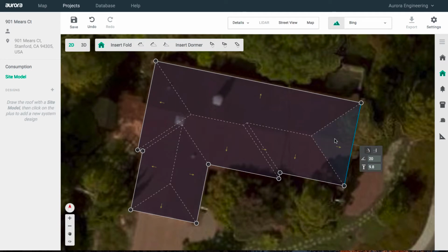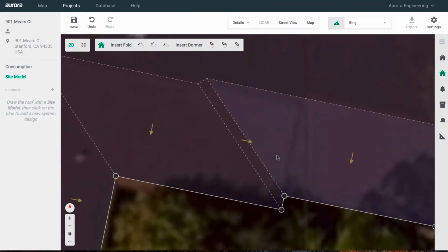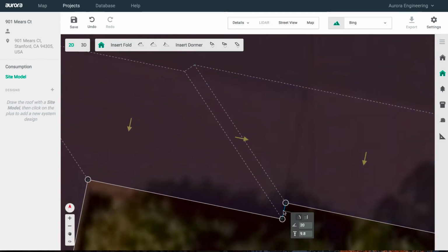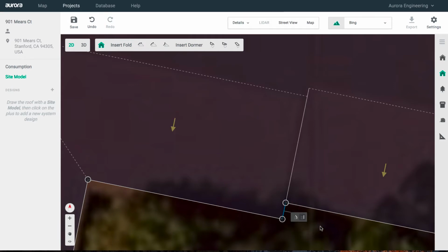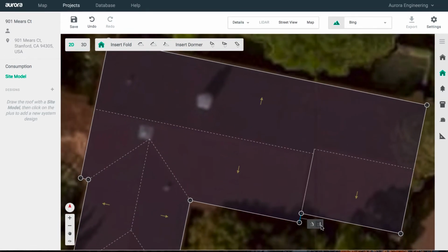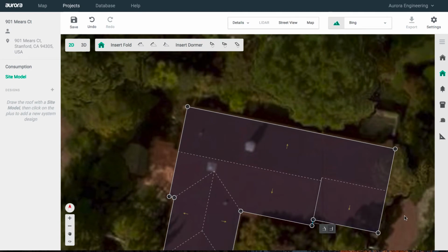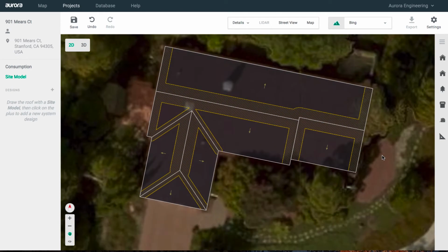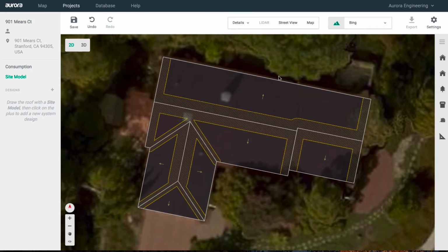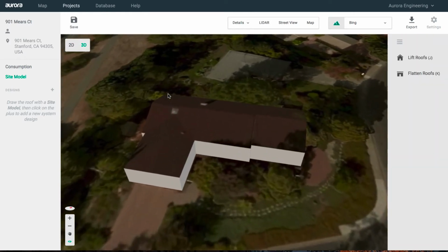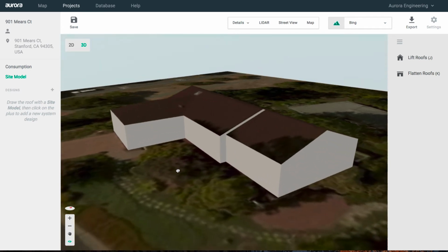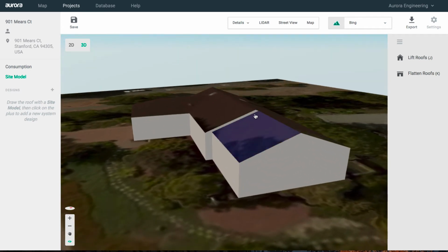Alright, next we're going to open up those edges because this is a central ridge line that runs across. And I'm going to do the same thing on the split edge. I click on it and I unpitch it. You can see that that basically causes the split to appear. Double click outside the roof surface in order for the setbacks to appear. Then I'll click on 3D, and in 3D space you can see we have a nice split as expected. Easy.